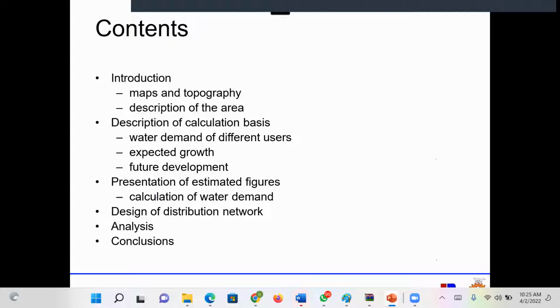So you are asked to design a water distribution system, a centralized water supply system, a water reticulation system. All of them mean the same thing. I'm just using them interchangeably. Whether it's a distribution system, a reticulation system, or a supply system, it simply means we want a centralized water supply network. So the first thing you need is a map, you need a layout. And that map must have topo. It's a map and a topography.